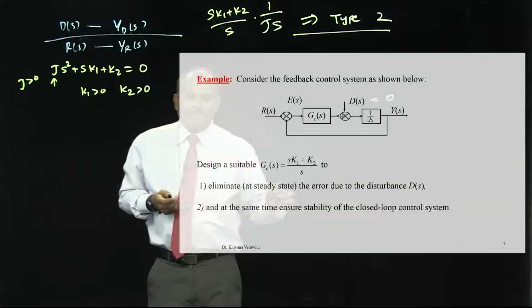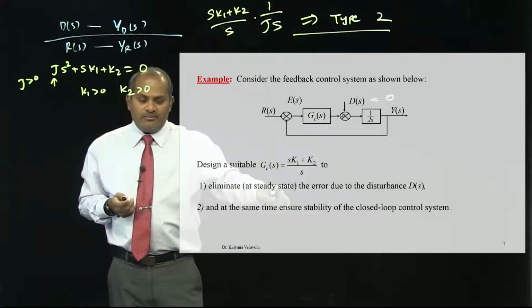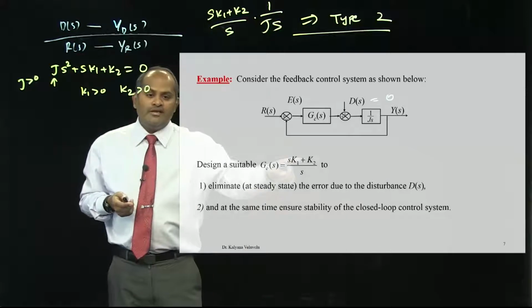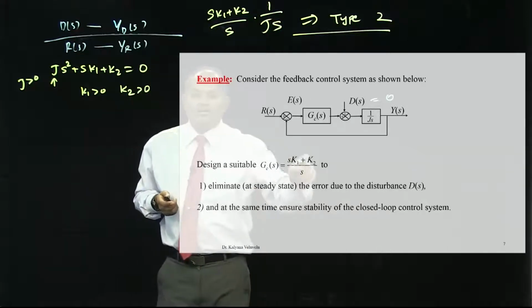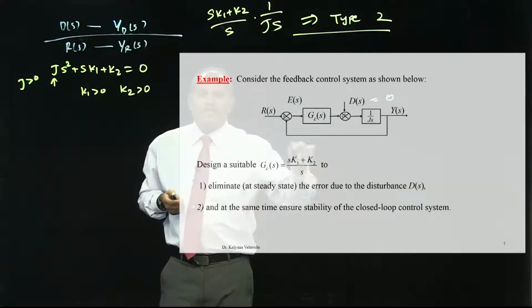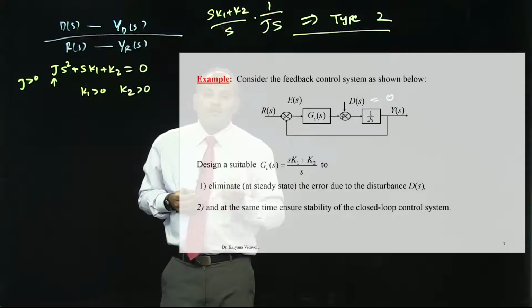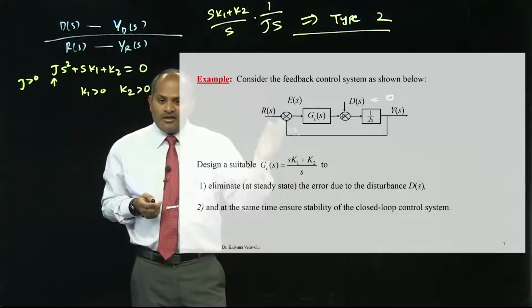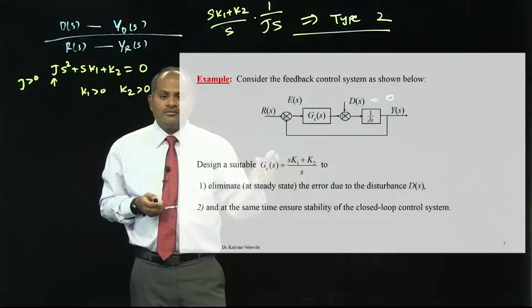So, in this way we can eliminate the steady state error due to disturbance and also ensure the stability. Means we designed. If you understand, this is the first time you are actually designing a controller. You will learn later that this is a PI controller. You will understand later, but the PI and PD controllers you will learn after the midterm examination.